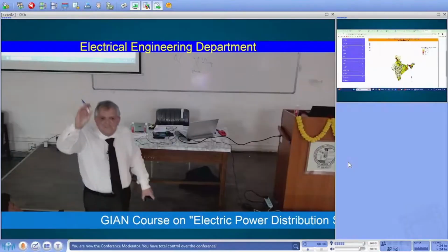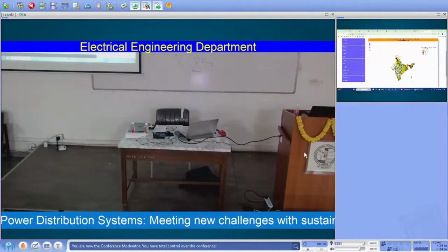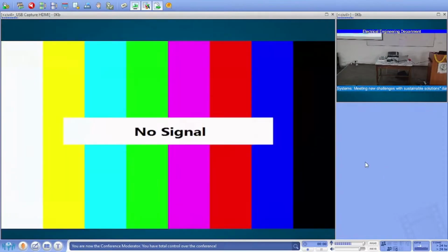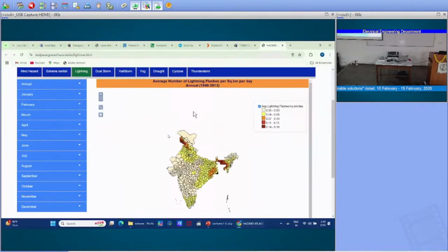We are not affected much by the charge of the leader of the initial path in the atmosphere, but we are affected by the current that is flowing in this path, that can have a peak of above 100 kiloamps. The median value for the events that are recorded is around 33 kiloamps. No? But we have events also that are above, not much above, but above 100 kA.